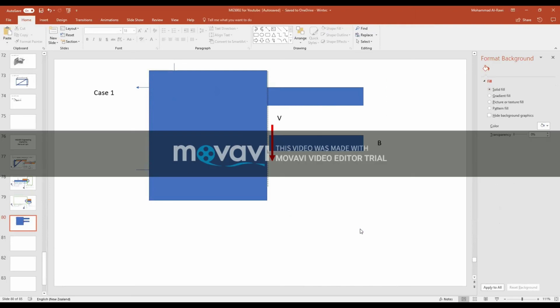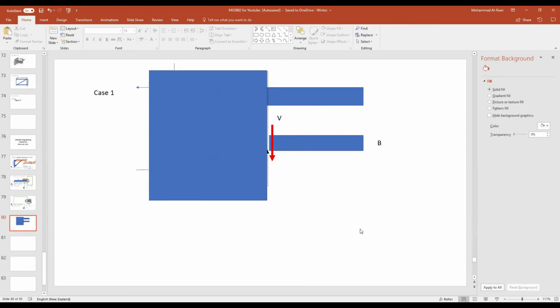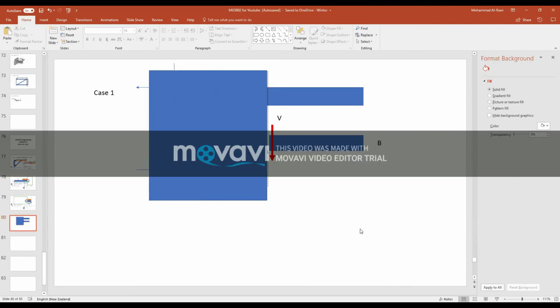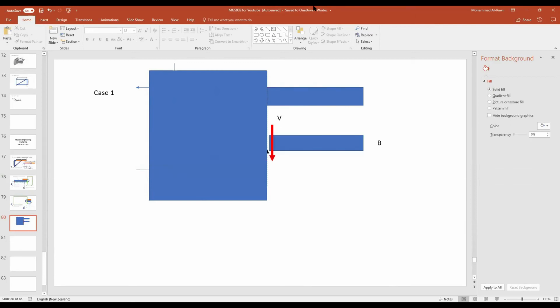And if you have a pen or a pencil and you really want to test how this works, you see that your finger from the top is pushing down and your finger from below is pushing up. Those different shear forces try to go, one upwards and the other downwards, and they will have the same value or magnitude but opposite directions to create that shear force. Shear force, I will call it the cut force, which is trying to cut the beam at certain points. Is it clear now? Hopefully. It's a good question you asked, guys.